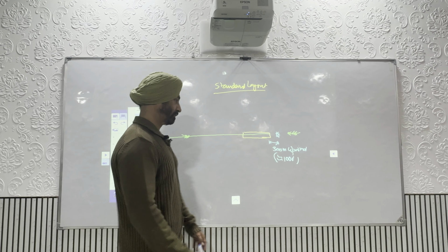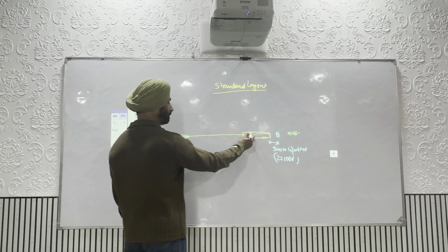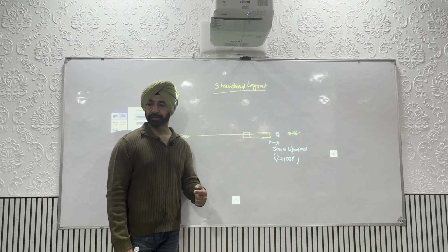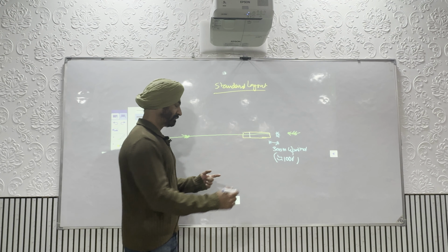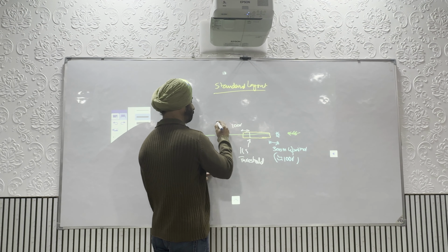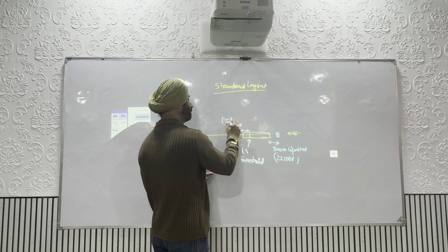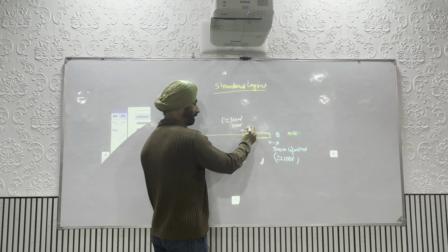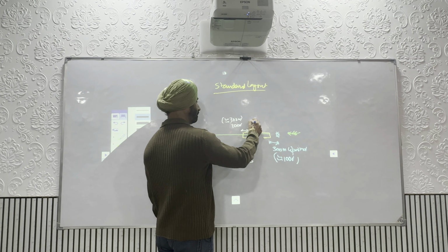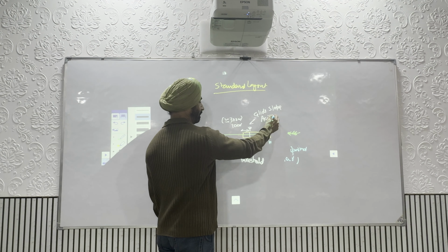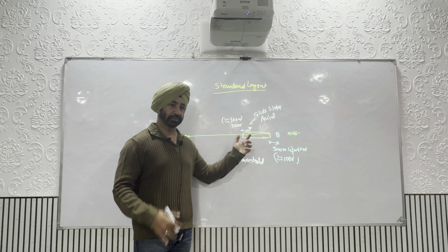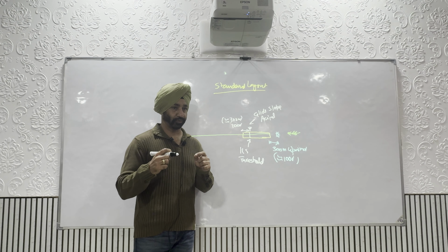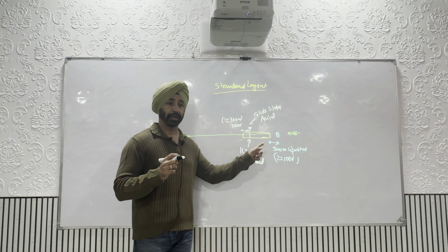So on an ILS approach, your touchdown point is 1000 feet from the beginning of the runway. The beginning of the runway is called the threshold. So the ILS threshold is 1000 feet ahead, which is roughly again 300 meters. Here on one side, normally on the left, you have the glide slope aerial or antenna. This is for safety, because this is the approach on instruments. So even if there are some inaccuracies, you are safer, you are going ahead.